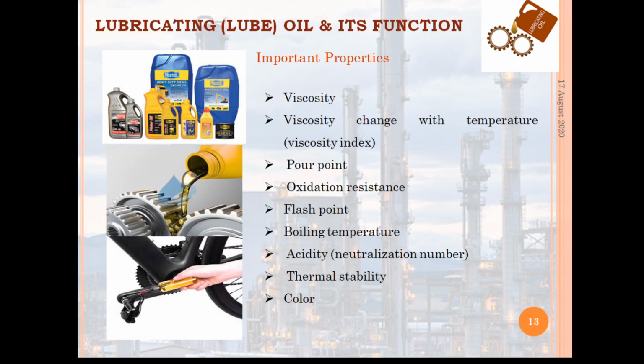So we have to know the suitability of that lube oil at those particular weather conditions. What is its pour point? What is its oxidation resistance, flash point, boiling temperature, thermal stability? How long can it be stable if there is a huge temperature generation?